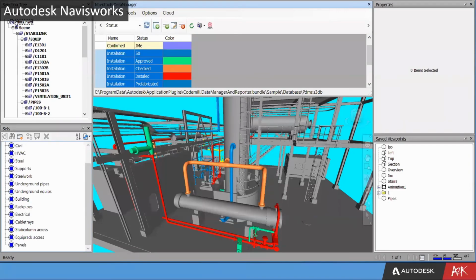And speaking of Navisworks, additional data can be augmented with the model. This data may be derived from other databases, which in this case here, could be data that represents an element's progress status, such as whether it's been fabricated, delivered, installed, and so forth. It might be augmented with operations data, so attaching things like warranty information, serial numbers, barcodes, installation dates, and so forth. Using the BIM and secondary data is actually a great method for visualization.